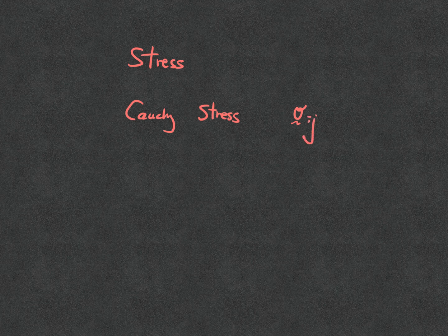Okay, so let me talk about another problem, which is the stress. Let's go back to the motivating problem. How many different types of stress would we need to consider? Stress as a tensor, the most famous one is the Cauchy stress tensor. Cauchy stress is sigma, and I will reserve sigma for the Cauchy stress forever, just to respect what other people are using. Cauchy stress has two current configuration indices, referring to the spatial configuration.